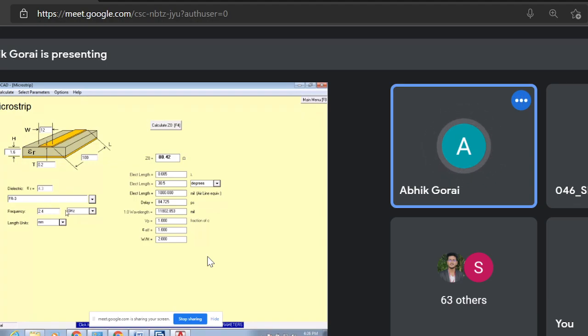2.4 gigahertz. Okay. Now let me choose, very interesting, the width of this strip line. Let me choose the width of this strip line as 4 mm. It is explicit in the problem that it is mm, because I have already set the unit as millimeter, right? So let us calculate. Once I set 4 mm, you get an impedance that is 41.52 ohms.